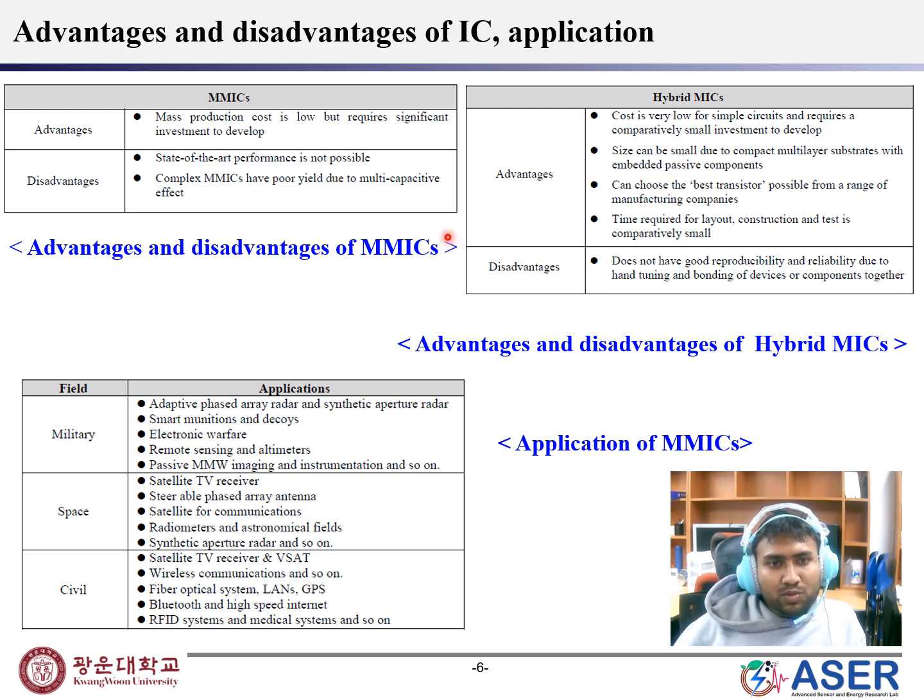Size can be smaller due to the compact multi-layer substrate, and the time required for layout, construction and test is comparatively small. The disadvantage is that it does not have good reproducibility and reliability due to the hand tuning and bonding of the devices or components together.